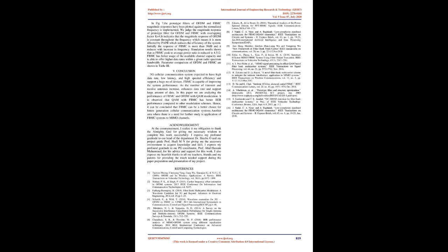Simulation results show that the FBMC peak to average power ratio is reduced to 4.512. FBMC has better usage of the available channel capacity and is able to offer higher data rates within a given radio spectrum bandwidth. Parameter comparison of OFDM and FBMC is shown in Table 3.